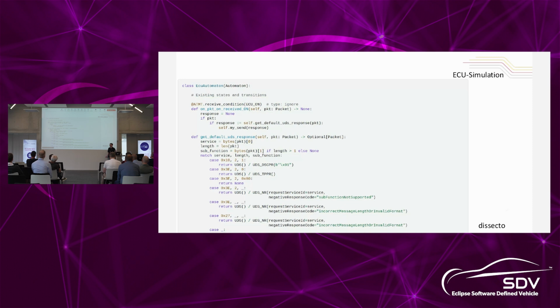So I'm a penetration tester. I want to crash stuff. I mean, simulating is cool for unit tests. What can we do? Turns out we need ECU simulation a lot more if we use Automotive Ethernet. The main reason is many protocols don't use the "I send a message on CAN and wait for an answer" approach anymore. Instead, we are doing handshakes.